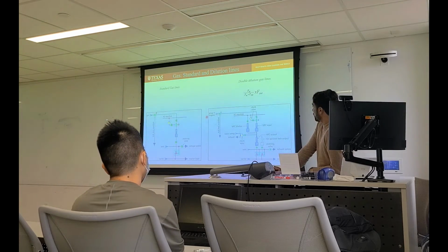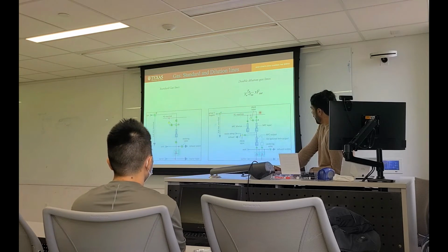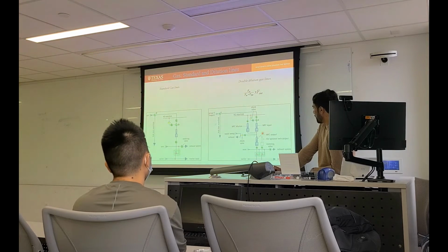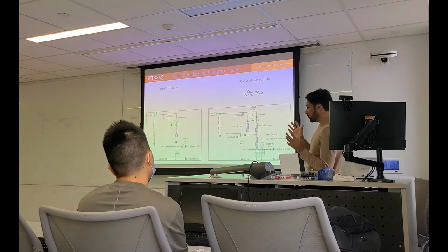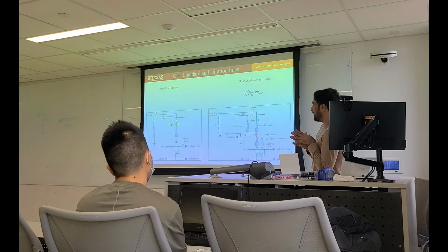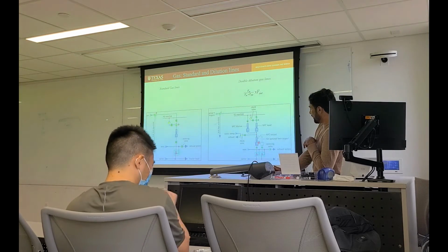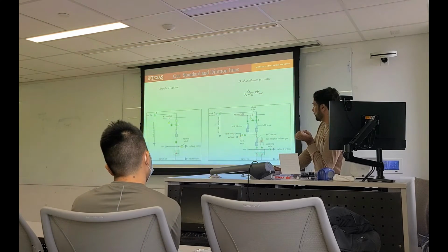Suppose we flow group 5, meaning NH3, or a dopant. I will talk about dopants later. We flow SiH4 gas, xylene gas, and then we mix hydrogen into it. The total mixture is around 50 SCCM, but we need only 20 SCCM from that. So we fix 20 SCCM at this MFC. The remaining will go directly to the baseline. That's why we have a baseline before this MFC.